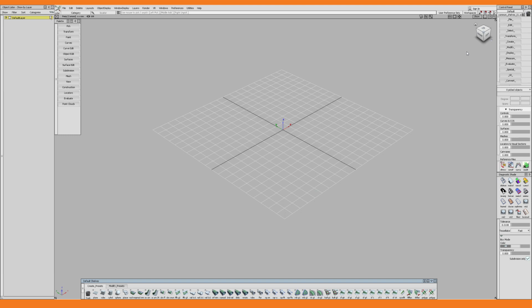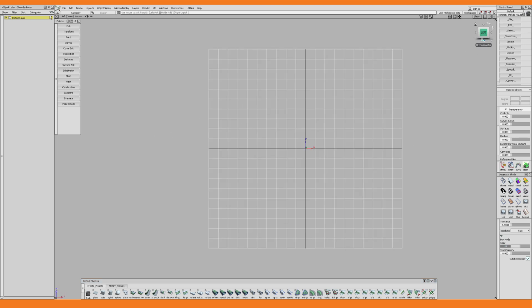According to my research, these AirPods are about 40.5 millimeters tall, so I want to create a distance locator with that same height and then match my canvas images to that distance locator. And if you are new to Alias and you don't know your way around distance locators, I will show you how to create one. First I choose the left view.